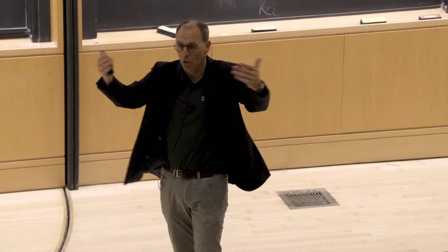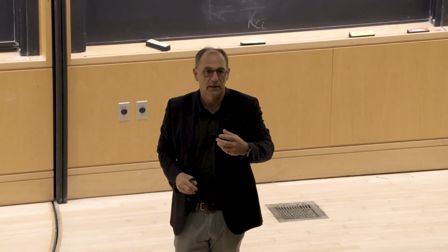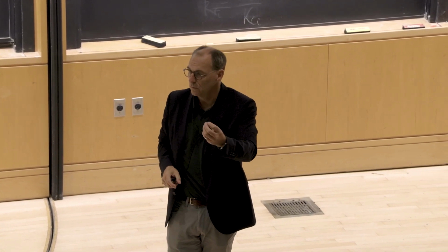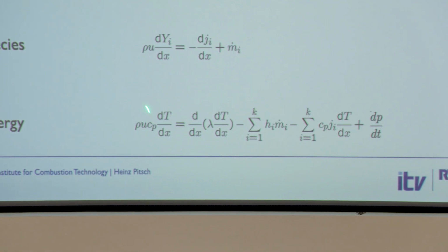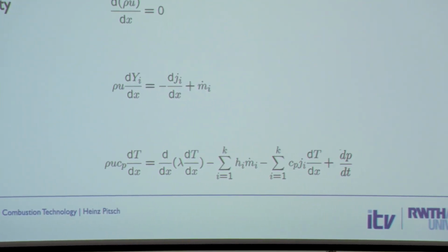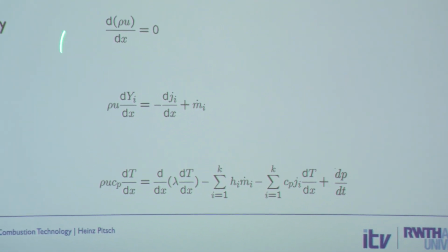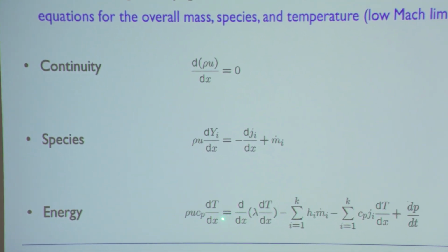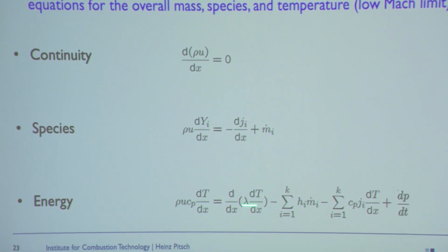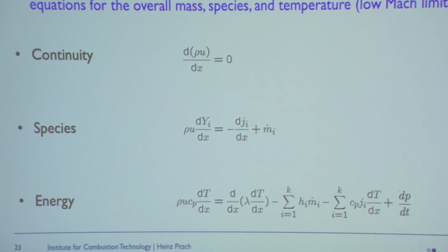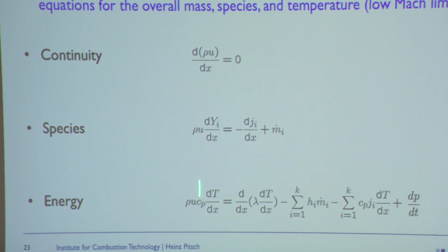And so that is called an eigenvalue problem. Eigenvalue problem means the system is overdetermined, and I have an eigenvalue, and there's only one value assigned to this that satisfies all the boundary conditions. And here in this case, rho u, or the burning velocity, is the eigenvalue, okay? So that's how we solve the system of equations. We solve it such that we satisfy 2 boundary conditions. With this, we assign 2 boundary conditions, and then rho u is fixed so that the 3rd boundary condition is also satisfied. Okay, that's an eigenvalue problem.